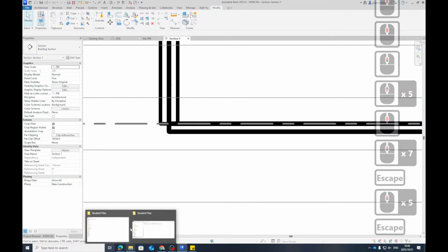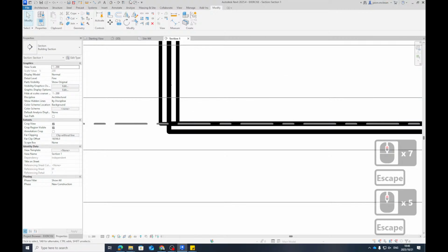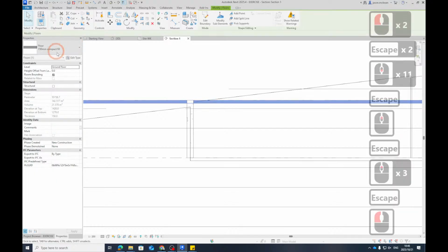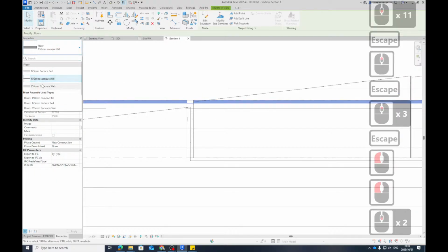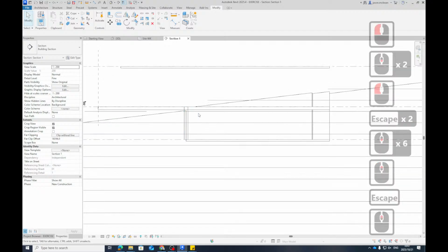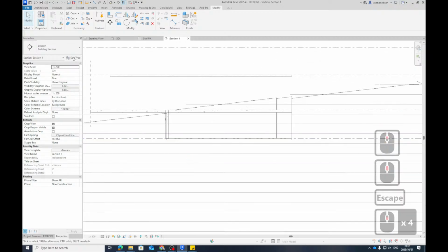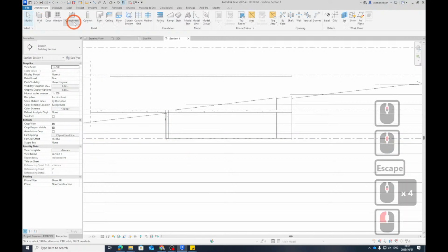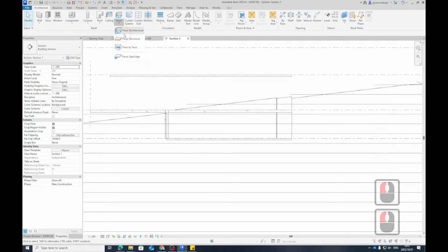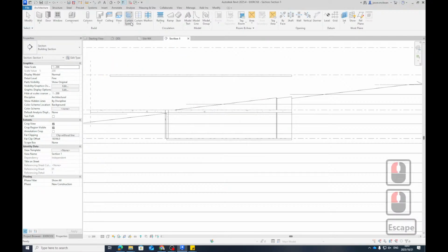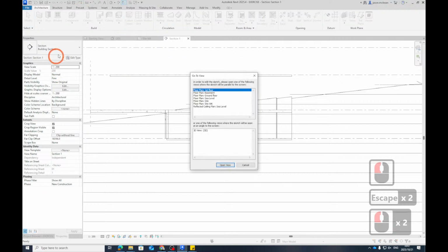So here's my concrete floor slab. Okay, now just remember these are quite thick, so these are typically going to be 255 because they're going to carry a load. These can be a bit thinner because they bear on ground. Okay, alright, so I'm going to add a new floor type to start fixing this. Architecture, floors, floor architecture. I'm going to add a new type. So, sorry, floor architecture. I'm going to do it in basement for now.